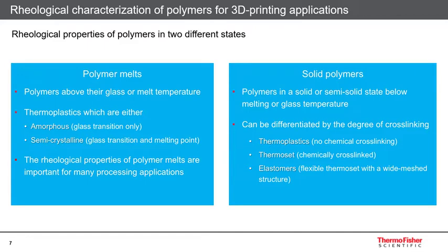Once the polymer melt is blended with other components or simply transferred into the desired shape, it's cooled down again below the melting point or glass transition temperature. Thermoplastic materials are not chemically cross-linked, and the process of liquefying by heating is reversible. However, if the polymer is chemically cross-linked, we distinguish between thermosets and elastomers. Elastomers are rubber-like materials that have, compared to the stiffer thermosets, a significantly lower cross-linking density. Elastomers and thermosets cannot be converted into a free-flowing melt due to the permanent chemical links between them.